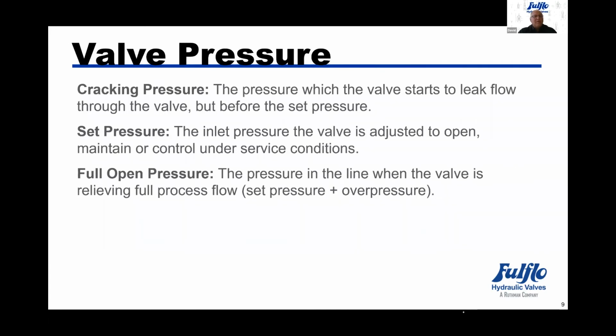The three most critical pressures that you'll find in a full flow valve would be the cracking pressure, the set pressure, and the full open pressure. The cracking pressure is the pressure at which the valve starts to leak a little fluid through the valve before the set pressure.